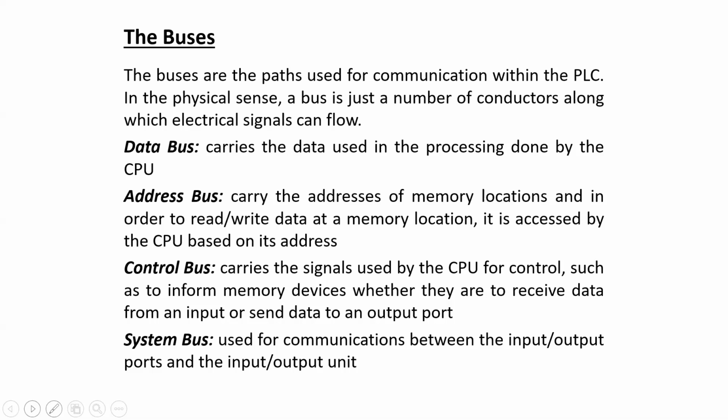And the input-output system bus is responsible for establishing connection between the input-output module and the external input-output devices, and also the programming device that is used to write the program into the PLC. So for those communications, the system bus is used.